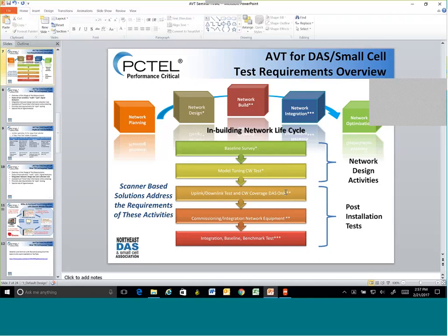So really there's a variety of things: connectors not tightened, dirty connectors with shavings in them, things being misconfigured, hooked to the wrong port, things not being connected. I was out on one test, we were walking around, we realized one antenna didn't look good on the AVT. We looked up and the antenna had been dismantled. It was only half there. So all sorts of things about how the construction and the installation configuration was done.